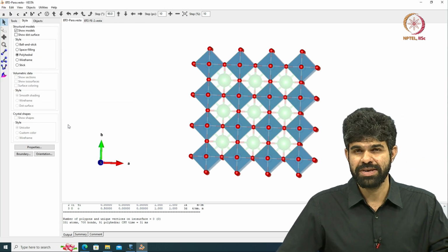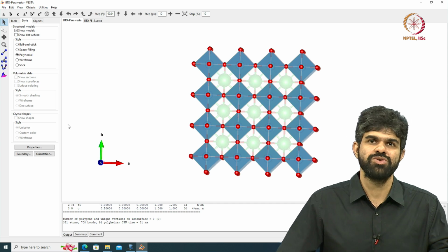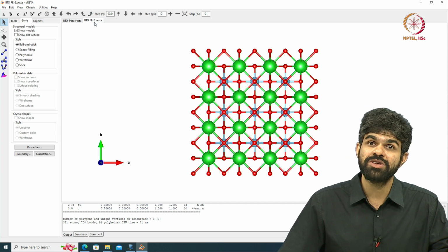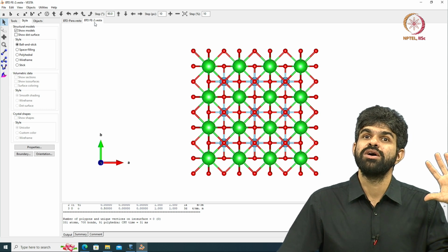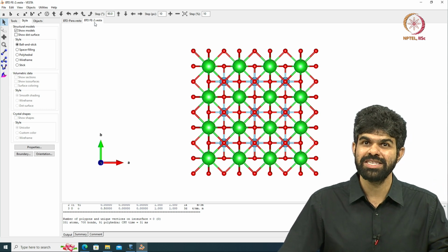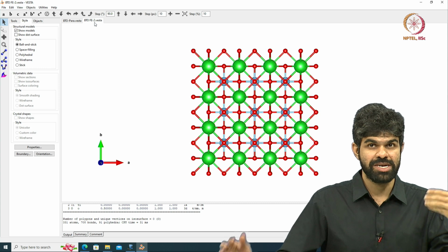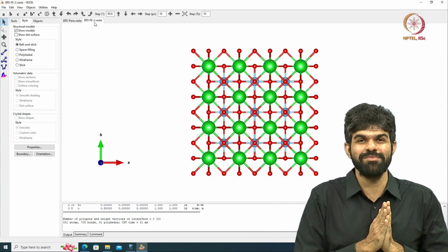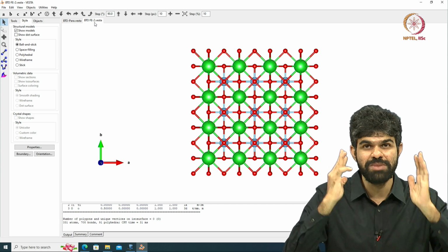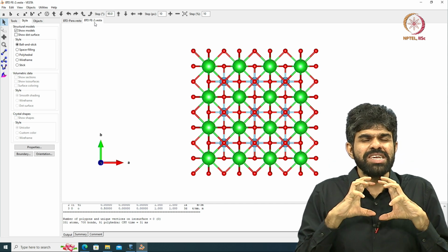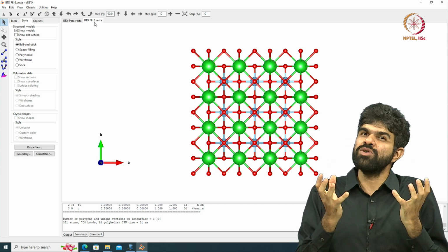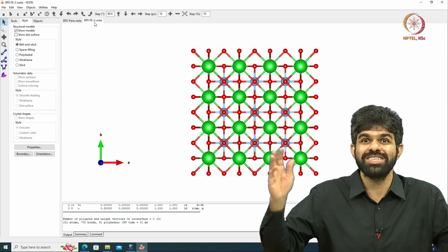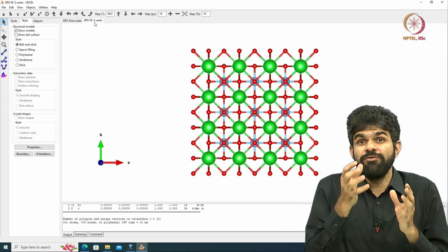Which is the boring phase, very symmetric. You do not really have the property of ferroelectricity here. If you want to get to the property of ferroelectricity, you should go to a ferroelectric or a polar phase, which is less symmetric. You reduce the symmetry, you generate new properties. That is the idea from now on. If you have to do any sort of material engineering, if I am going to really high symmetric materials, the amount of properties that I can extract, fancy properties like ferroelectricity, piezoelectricity, etc. If I want them.